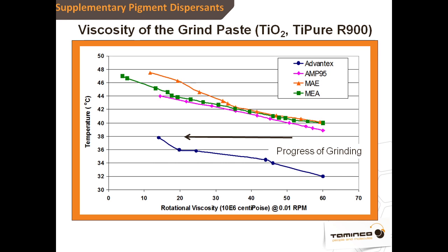I could suggest that if you had a bottleneck in a pigment grinding operation, if you were space limited in a pigment grinding operation, there might be an economic value here and that you could grind more pigment in the same amount of time if you were to use multifunctional AAAs as compared to less functional, very hydrophilic, simple alkanolamines or ammonia type base.